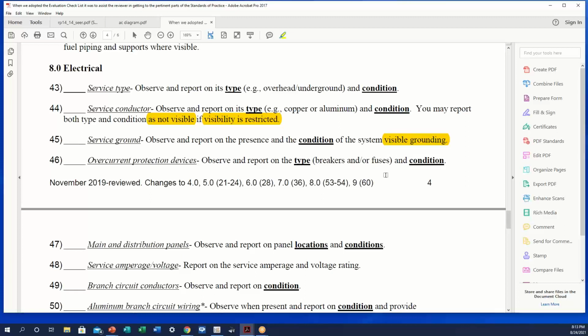So if I have a main panel, I have to report that the breakers in the main panel appear to be functional. Yes. Okay, and if I have a sub panel inside with fuses in it, I can say that the 30 amp Edison based fuses are functional and are okay, or should I say an electrician should verify their safety and upgrade if necessary? The second part. It should be verified for the safety. Okay, does everybody understand? I can have a good service outside that's been upgraded, and inside I could have a service with fuses and pennies underneath the fuses that make this house unsafe.